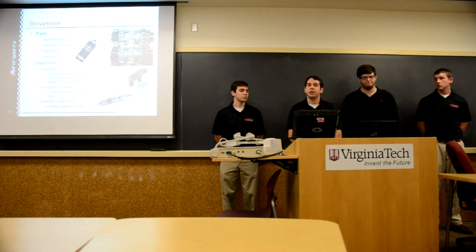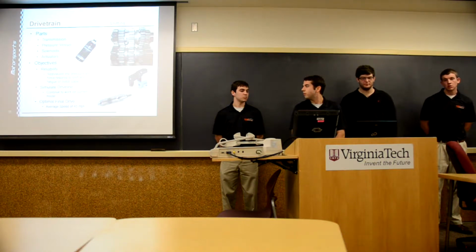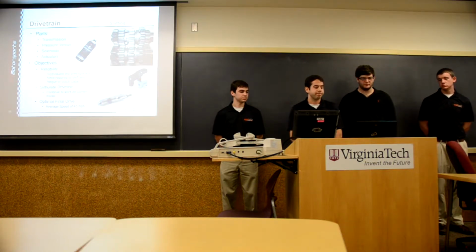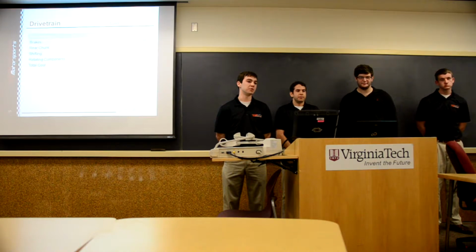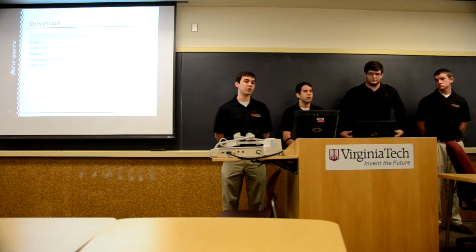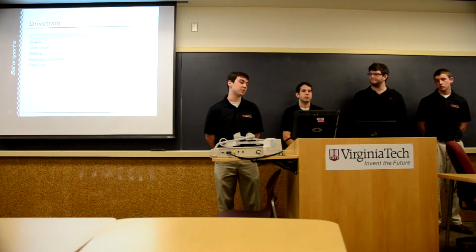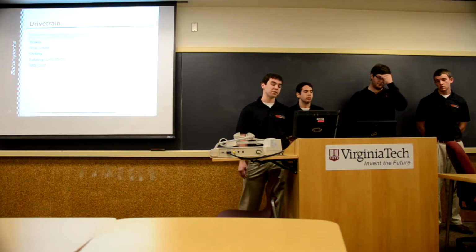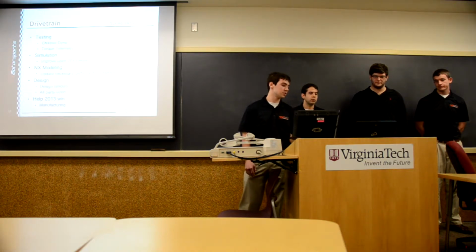Also, I'm going to continue the simulation of the driveline, as Alex has worked on, and use that to reevaluate the optimal gear ratios with the new engine, and design for the final drive with an average speed of 45 miles an hour. As we said before, a lot of these improvements are good, but we've done a lot of work and we have low masses as it is. To improve on that and keep our masses down and even reduce them some, we get into high costs because of low tolerances and other manufacturing demands. So we're looking at anywhere between $7,500 to $10,000 for the 2014 drivetrain, just to keep everything good.